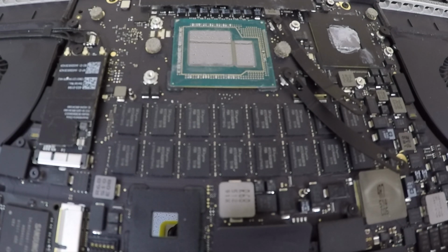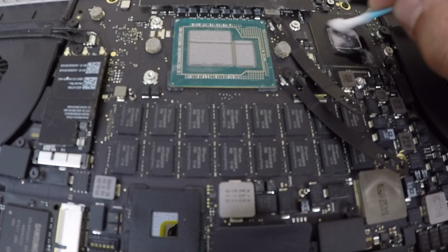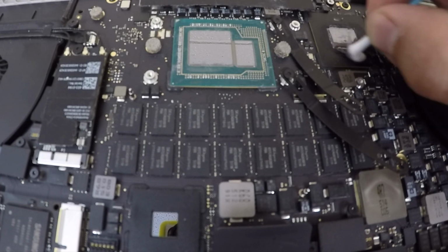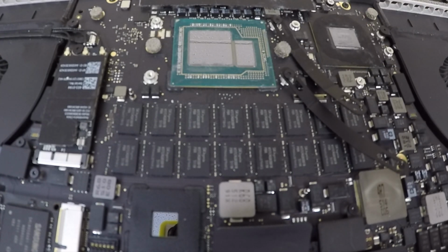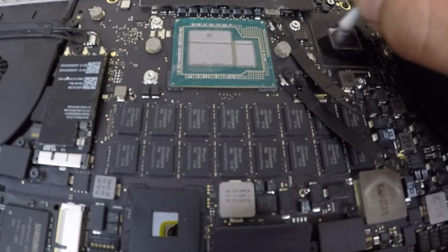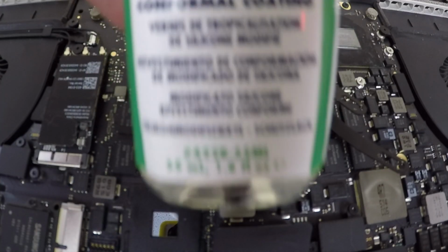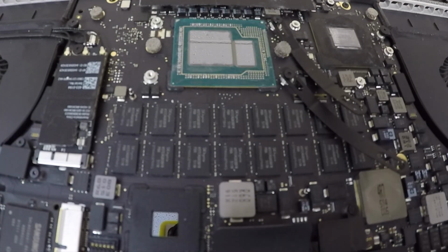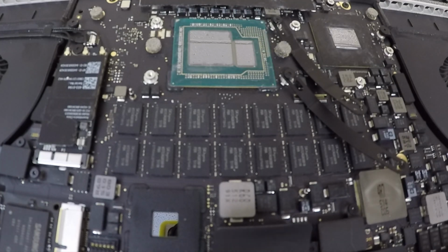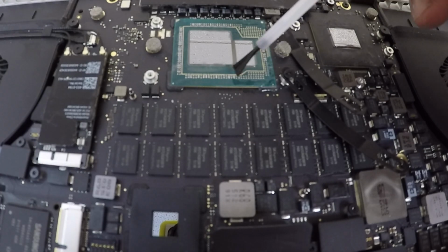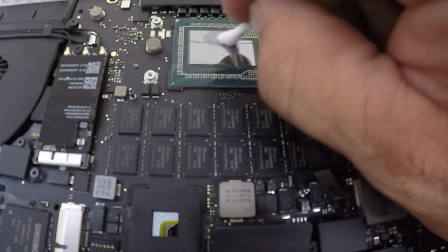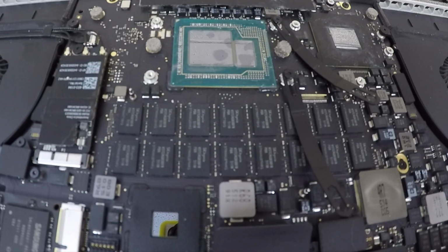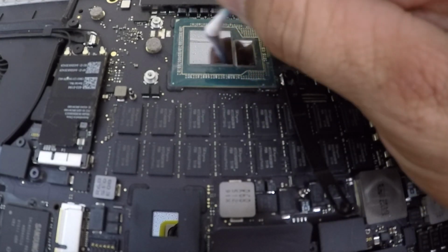Next, you're going to take your Q-tip and 90% isopropyl alcohol, and you're going to scrub and clean off all the thermal compound on the CPU and GPU. Now, I've already done this process on the CPU and removed the tape that came from the factory. I'm now going to take the conformal coating and I'm going to apply several layers to the CPU board to ensure that no shorts occur if the liquid metal were to touch the board. Now I kind of went overboard and did several layers. It's up to you. I'm also going to make sure I clean off the CPU and get it completely ready.